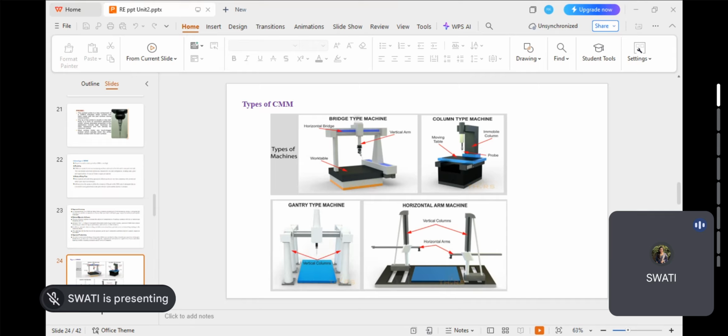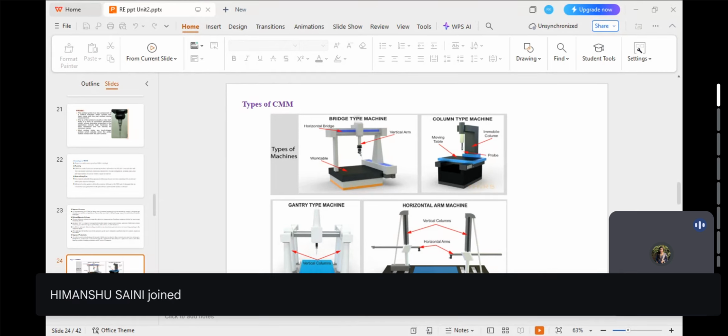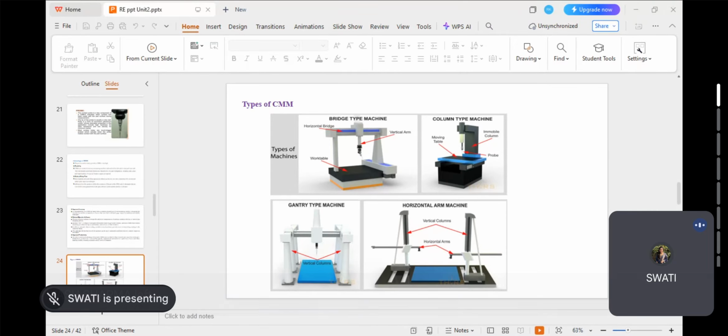You can also go for pre-assembly qualification of parts, meaning you can dissect the different components, individually check all parts, and see whether these parts are qualified for this particular single component or not. If it is, then you can go ahead. If it is not, then you have to improve it. So there are a lot of purposes of the CMM other than reverse engineering, or collecting cloud points only.